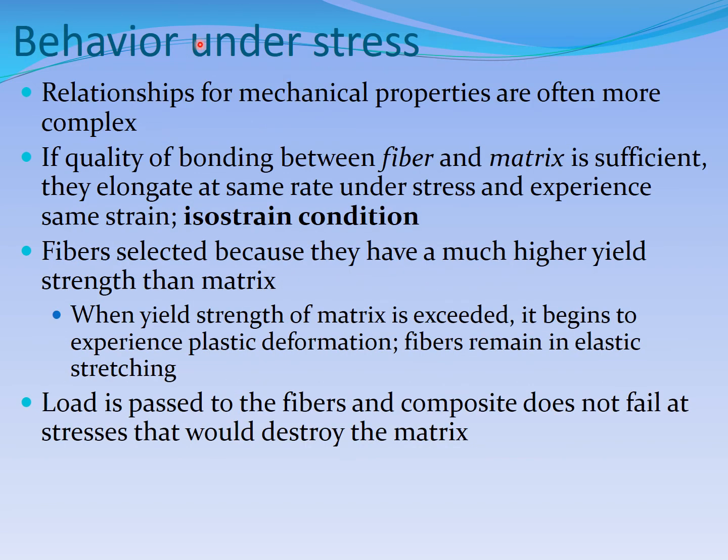Behavior under stress. We are talking of strength first, right? Relationships for mechanical properties are often more complex, right? For conductivity and density and so on, simple rules based on the previous page, but for mechanical properties it may be more complex. If the quality of bonding between the fiber and the matrix is sufficient, they elongate at the same rate under stress and experience the same strain. This is called the iso-strain condition.